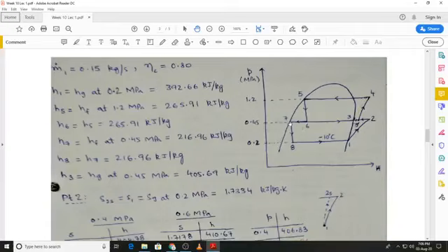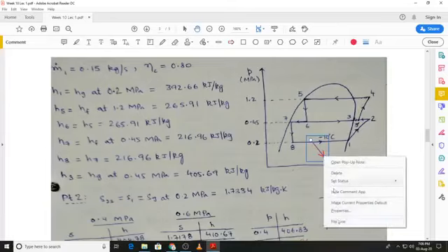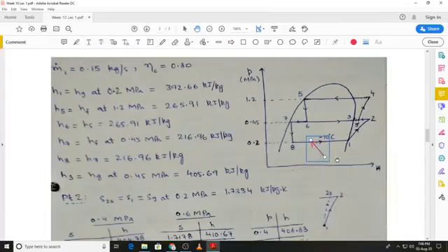And then the liquid that we have separated in the flash tank is further throttled to the evaporator pressure and reaches state 8, then goes into the evaporator where heat is removed from the space. So this is the heat that is removed from the space, so this will be QL over here.